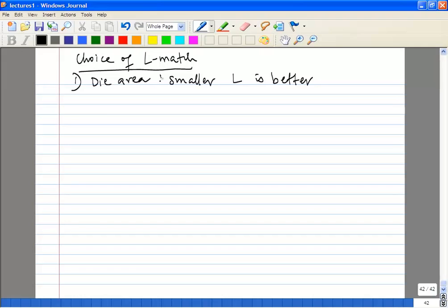The reason is you would use less die area, and one more reason is many of these inductors are not ideal inductors when you look at on-chip values. So what that means is if you use a smaller inductor, it is quite possible that your losses might be lower. Okay, we'll look at it in a couple of classes. We'll look at how to design on-chip inductors.